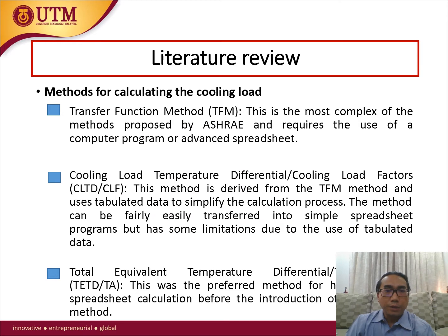Methods for calculating the cooling load. Number 1, Transfer Function Method, TFM. This is the most complex of the methods proposed by ASHRAE and requires the use of a computer program or advanced spreadsheet.